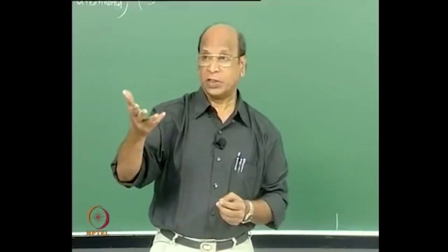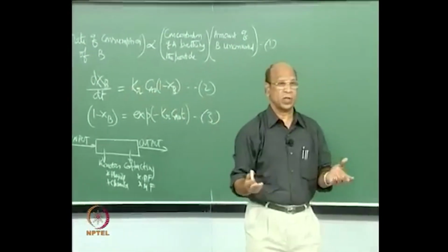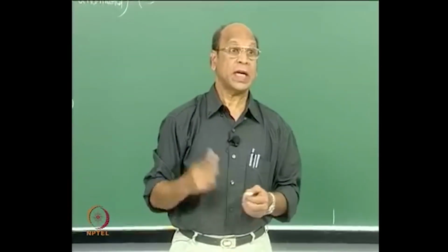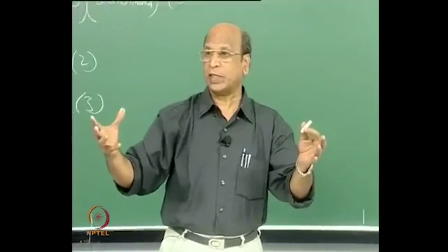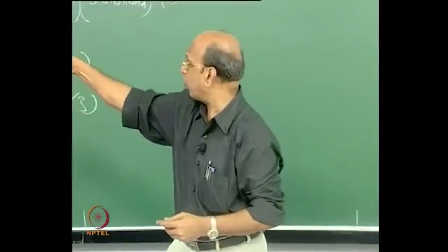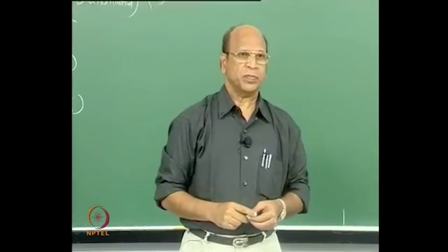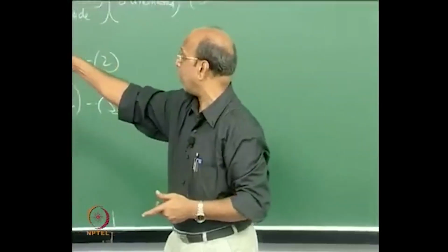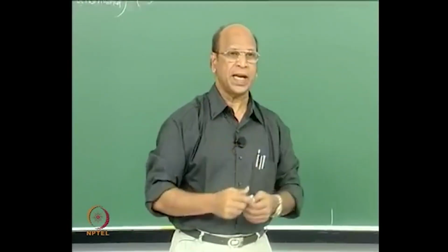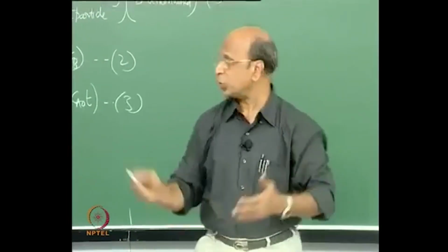If the reaction is very fast, but here when you derive this, the automatic assumption is that it is rate controlling. What is rate controlling? Reaction is rate controlling. I have large pores where the diffusion is very free, just going inside. Okay. So, automatically when you say homogeneous reaction model, that is only the reaction control, but actually that is also true. When you have a very fast reaction, even though I have a porous particle, that behaves as if it is a shrinking core model. So, they are beautiful things, and these two are the basic models.